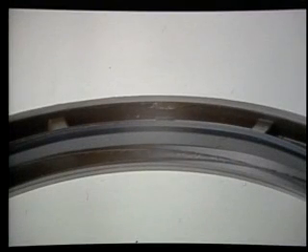A new Viton Teflon seal has recently been released as a service replacement for the 14337 or 19109 oil seal. The secondary lip of this new seal, part 21036, is made of Teflon. Because of the self-lubricating qualities of Teflon, the radial pressure is increased between the secondary lip and the yoke. The tighter fit helps prevent contamination from entering the seal.